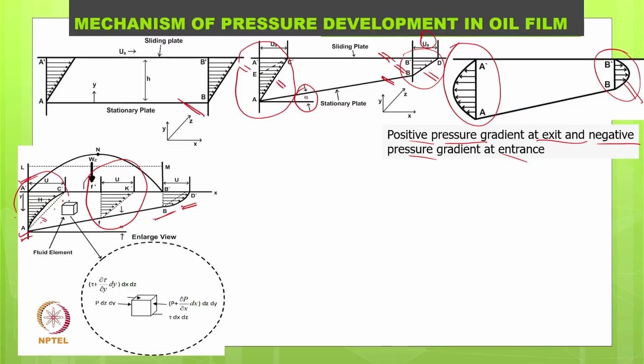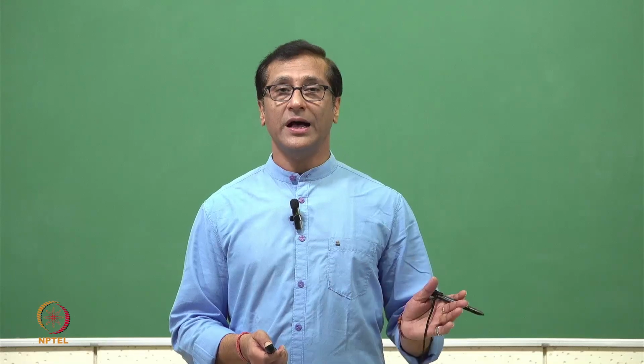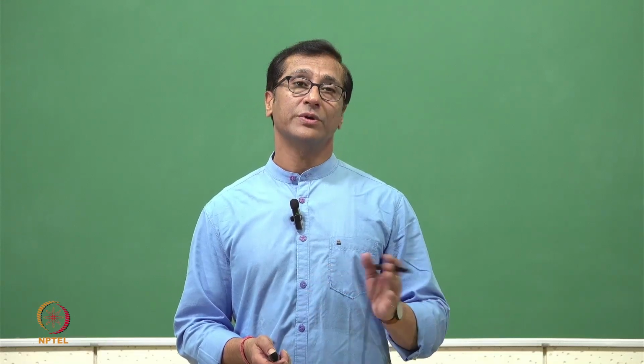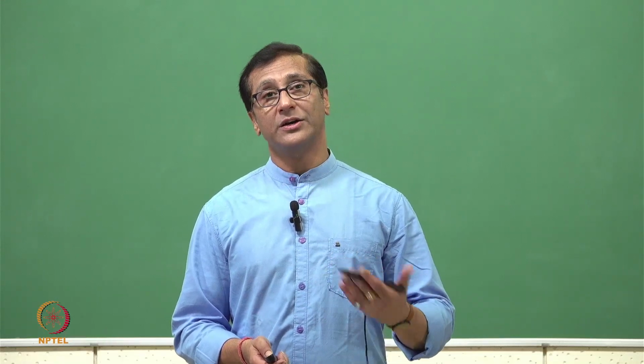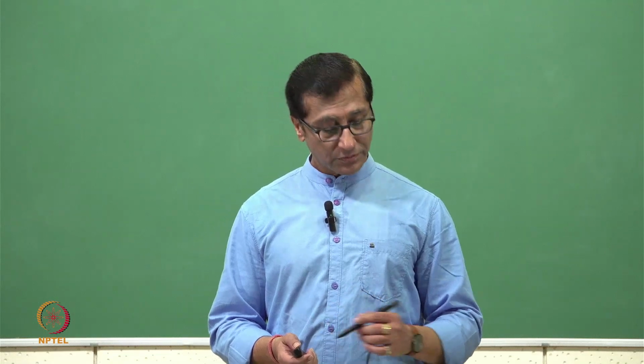So if we provide a pressure input here, I'll show you in the next slide in a figurative manner how we do it. So this is a good learning. I can really reduce a pump pressure, and still I get a good lubricant layer in a hydrodynamic lubrication mechanism.